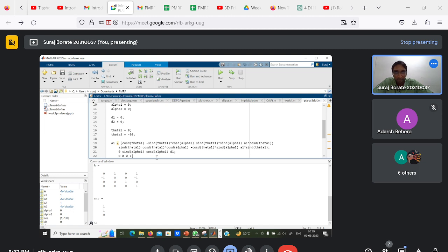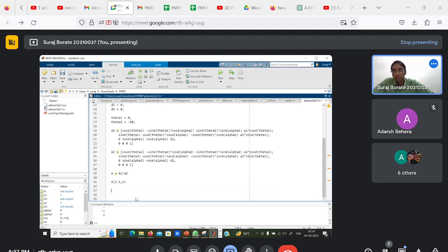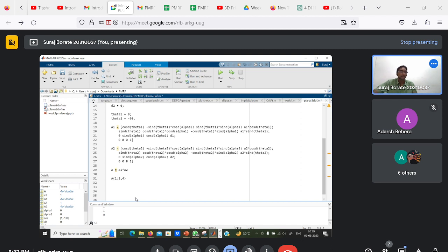Fine. Let's say you want to visualize this. As I had told, the application of forward kinematics is basically visualization. For control you will use inverse kinematics, because you know where your end effector should be placed. If you are doing welding, you know where the end effector should be. What you don't know is how the robot should move to do this, right? What should be the joint angles? So that is inverse kinematics, that we will see in the upcoming lecture.